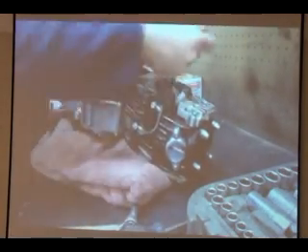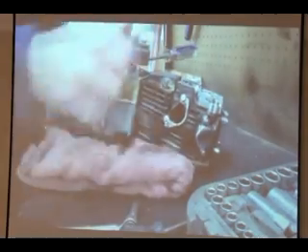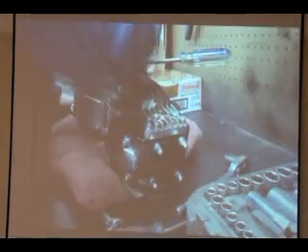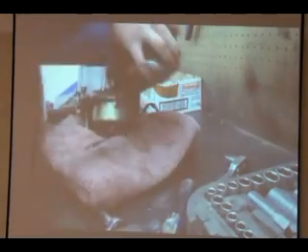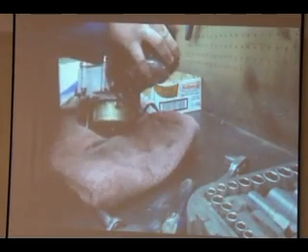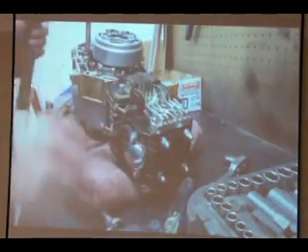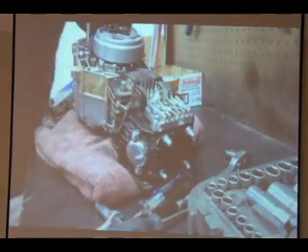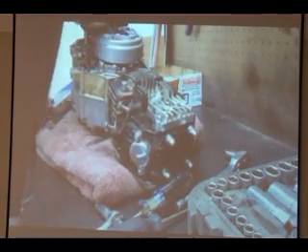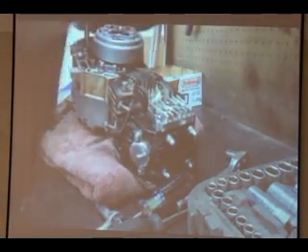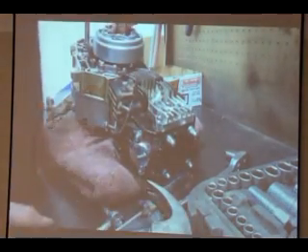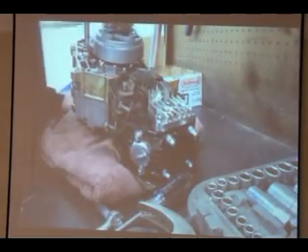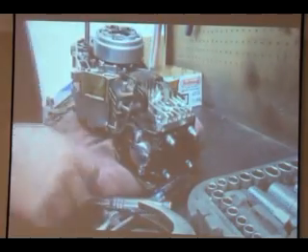Can somebody tell why it is so difficult to remove this particular part? The rotation and the locking direction of the thread are one and the same. So in the process of rotating itself, it will get locked. It is designed in such a way that the direction of rotation and the locking direction of the nut are one and the same, so that in the process of rotation, it doesn't loosen. So now to dismantle it is very difficult.